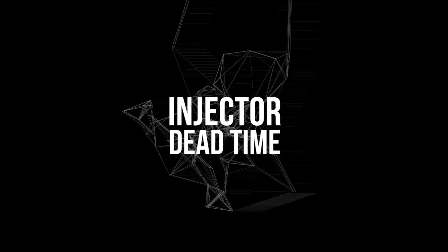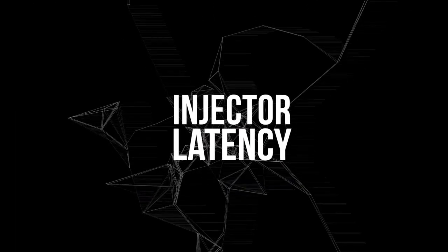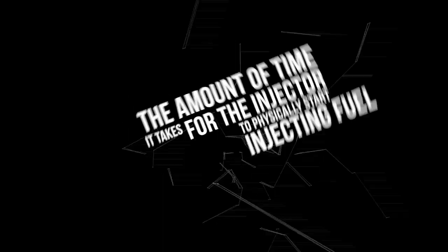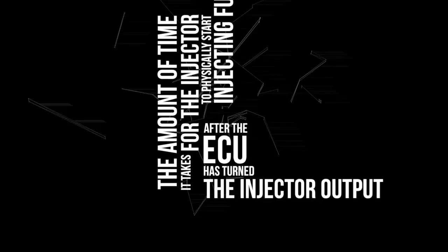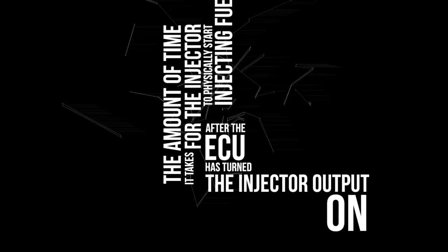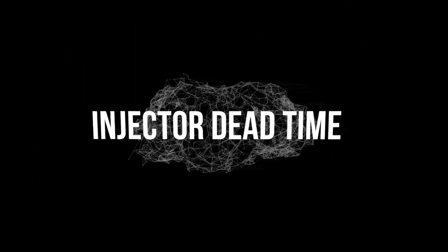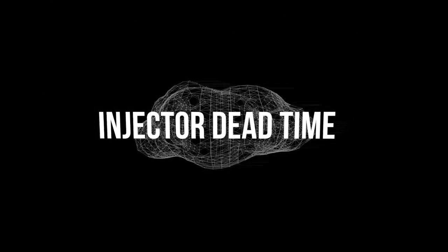I'm sure that you would have heard of injector dead time or injector latency by now. This is the amount of time it takes for the injector to physically start injecting fuel after the ECU has turned the injector output on. Think of it this way, when the injector output opens, it takes a certain amount of time for the injector pintle to start to move and to get to the point where fuel starts to flow through the injector. This is known as injector dead time, the amount of time it takes for the injector to start flowing fuel after it's been turned on.